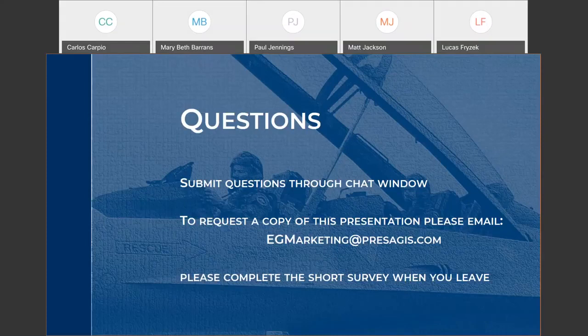Matt, this question is for you. The latency values that you mentioned in this presentation, are they based on some kind of human factors standards? Can you comment quickly about that? Yeah, some of the numbers there, the 180 milliseconds, is from general human factors. If you look in the ARINC 661 standard, it talks about anything beyond 180 millisecond latency. For some of the newer ones, these are based on research, so they're not standards. They're studies that have been performed and are available, and I've collected some of these numbers together.